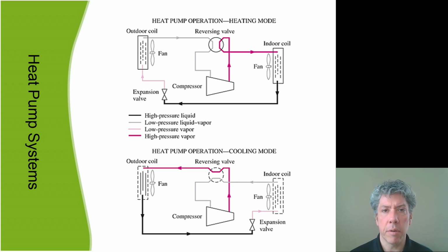So anyway, continuing with the heat pump mode, the relatively low temperature but still high pressure gases go through an expansion valve, and now they have to expand to a fairly low temperature. And one of the problems is that it's difficult to make the expansion happen in such a way that you don't go too low in temperature. And so to really gain heat from the outdoors when it's cold, most people don't really think about turning on a heat pump necessarily when the temperature is, say, 50 degrees.